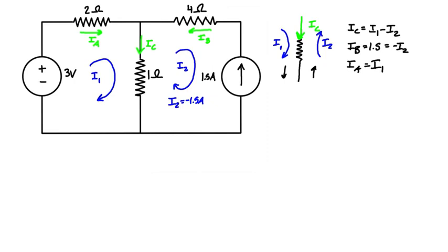Now, when you're doing mesh analysis, it is most common to write your mesh currents, which are I1 and I2, going clockwise. And if you basically always draw them clockwise, it just reduces your chance for screwing up later, especially when you come into situations like this, because you always have the same form here. So that's always the first step in mesh analysis, is to draw on the mesh currents and write down any information that you have. For example, in this case, we were able to solve what this one is really easily, and then even based on that, we were able to find out what one of the actual branch currents is in one of these elements. Generally, to find the rest of the information, we're going to need to apply KVL, Kirchhoff's voltage law, in each loop.